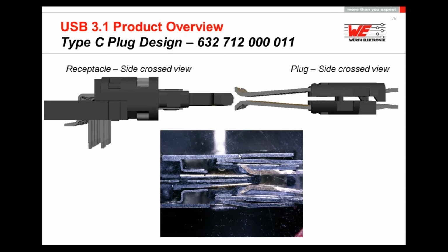Well, in the market, often I hear comments like, well, this is to recognize in what way the mating part is plugged in. But that's information that is definitely wrong, because like I told you in advance, in which way the mating part is plugged in, we will recognize by analyzing the CC1 and CC2 signal. So that's the data where we transfer this kind of information.